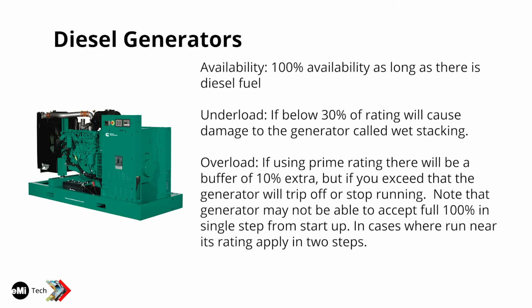Note that generators may not be able to accept the full 100% in a single step from startup. In cases where it is run near its rating, apply in 2 steps. I've seen sites, especially one in Cameroon at a hospital, where when they tried to put the full load on it, when they transferred over, it would just die. It's because they were right at that limit, and especially as it gets older too, when you transfer it over, half the time it would just die. The way to solve that is just apply in 2 steps. The generator can then take the full load.